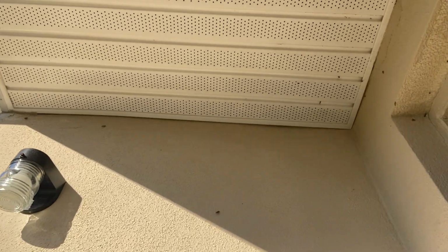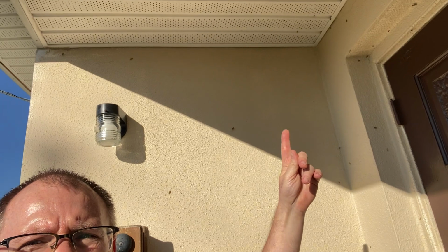Talking more about this home we're doing an inspection on, one thing I noticed too was where the soffit vent meets, there's a big gap right between the soffit vent and the stucco. These are great areas to do exclusion work with caulk or silicone because once you seal up areas like that, you're really going to do well to keep the insects out. Can you seal up every little inch of the property? No. But think about it as a company. This is an extra service you can provide that's needed by the homeowner, and you can help keep the insects out. To me, it's a no-brainer to offer services like this because it fits right in with our IPM programs.